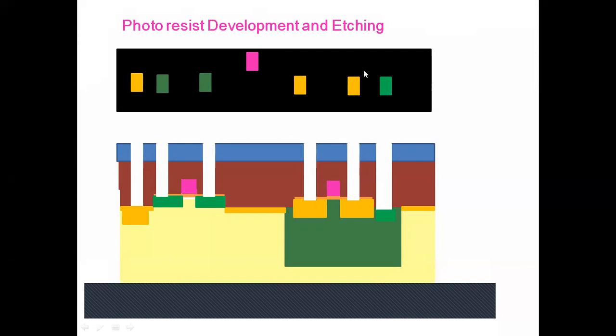We have to connect these two together, and we have to connect these two together, because this is the drain of NMOS, this is the drain of PMOS. In a CMOS inverter, these are connected together. Now this is the source of PMOS, this is the substrate of PMOS, and these are connected together. This is the source of NMOS, the substrate of NMOS, and these are connected together. And this is the gate. You cannot see it in cross section. The cross section is taken across this, but if you take the cross section, you can see this back contact also.